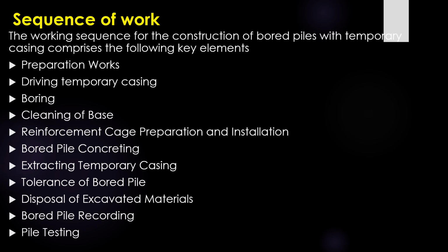The eighth step is to check the tolerance of the bored pile to ensure it meets design specifications. The ninth step is we dispose of the excavated materials from the site according to environmental regulations. Bored pile recording is the tenth step, which is very essential. We record all details of the bored pile construction for future reference.